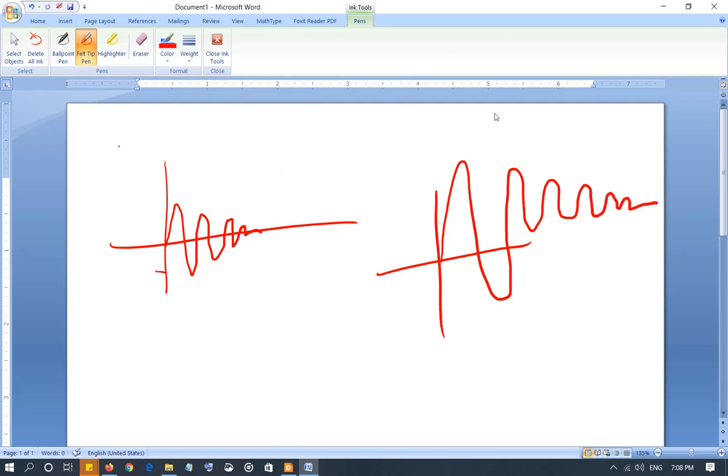So for the resonant pulse inverter, the idea is that if we can capture this thing right here, this is almost a sinusoidal waveform, half of the sinusoid waveform. It is of course affected by an exponential decay, but again, if the frequency of this sinusoid is much larger than the rate at which it is decaying, then when we catch this, it is not going to be a lot affected by the exponential decay.